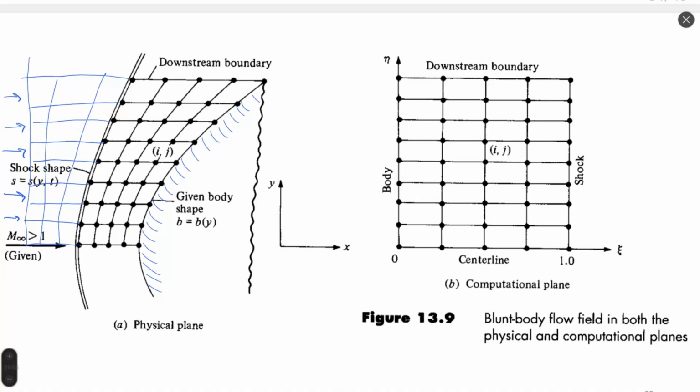And when we have this preliminary simulation made, we can save a lot of computational power, or we can significantly improve the quality of the solution once we move these nodes inside the space between the shock wave and the body. Or simply by removing this part of the mesh, we can save a lot of computational power and a lot of time for simulation.